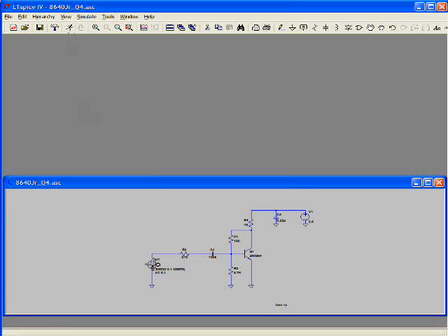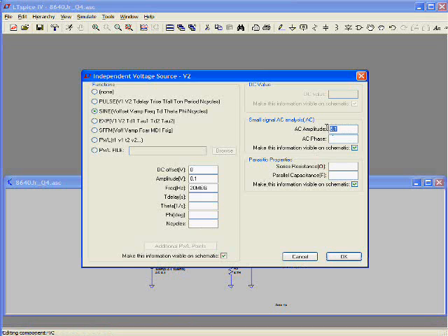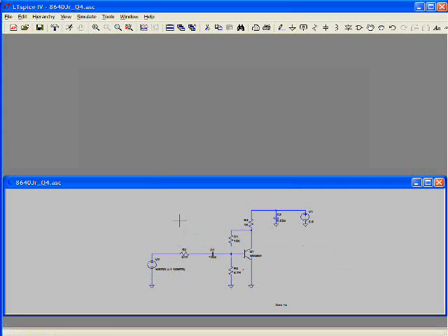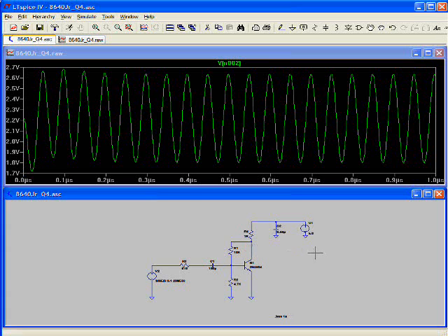And let's escape. Right click this and get rid of this part again. So now we're back to just a set frequency for the sine wave. Save that. Run the simulation. And look at our output. Still looks pretty good. So that's how it works.